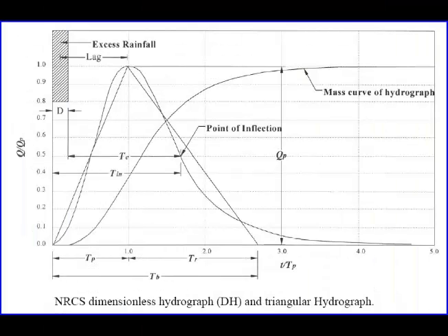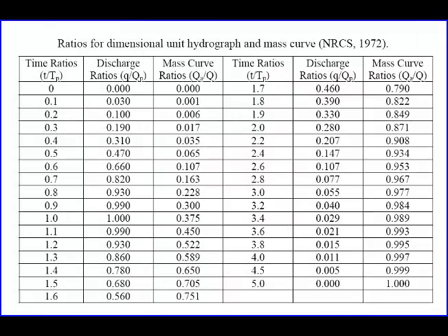For the inflow hydrograph, the program uses the NRCS dimensionless unit hydrograph. In an event-based model such as the NRCS method, the rainfall hydrograph for the design rainfall event is based on the CN method, and the application of the NRCS 24-hour rainfall distribution is well documented.